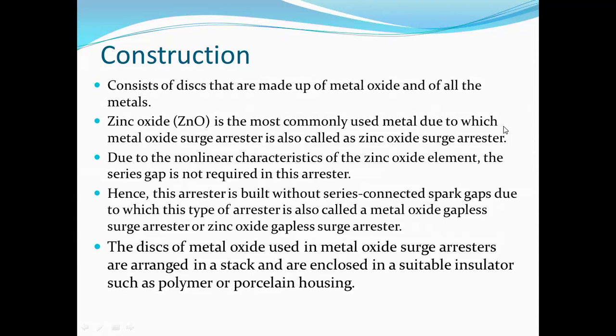Due to the nonlinear characteristic of the zinc oxide element, the series gap is not required in the surge arrestor. Actually, in a conventional surge arrestor, we place a gap in between the two rods. But the characteristic of zinc oxide is non-linear, so the series gap is not required, and hence this arrestor is built without series connected spark gaps.